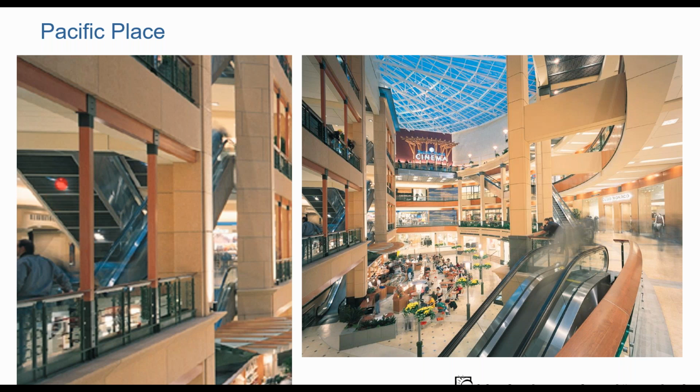These tubs weren't even supposed to happen. This is another thing that kind of went wrong. This was another VE. They decided that it would be better to have compact fluorescent tubes as emergency lights. So most of the time, the emergency light was on instead of the actual light that was supposed to be there to light the